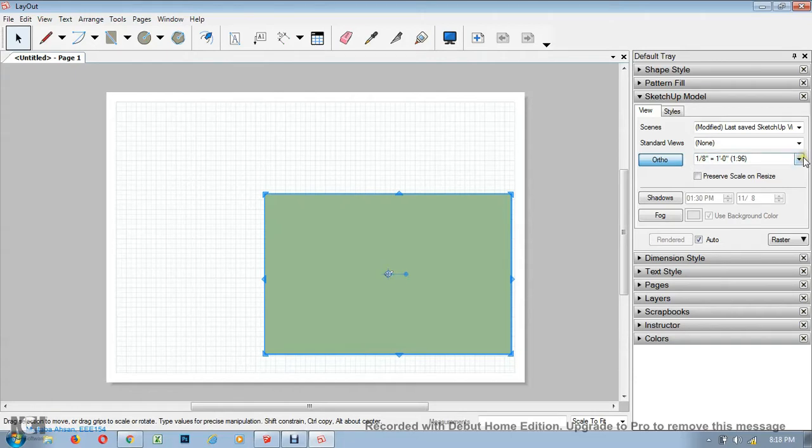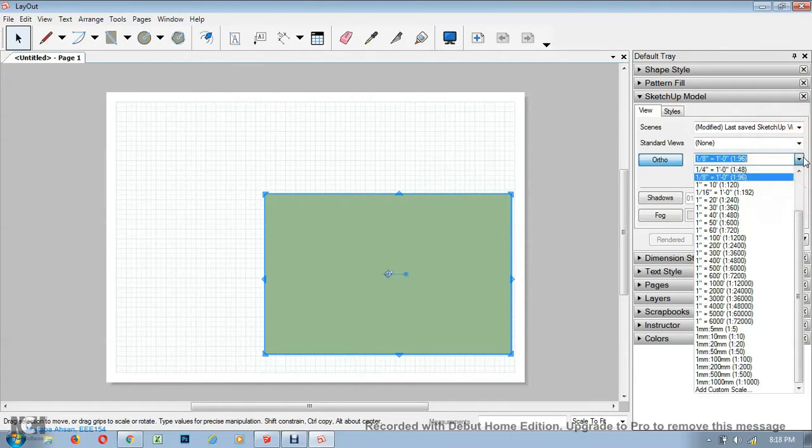Once you click that, the drawing gets pretty small, and the scale is 1:8 inch. But if you remember, we drew in centimeter scale, so we'll look down here somewhere. There are different scales here. So if I select, let's say, 1:10,